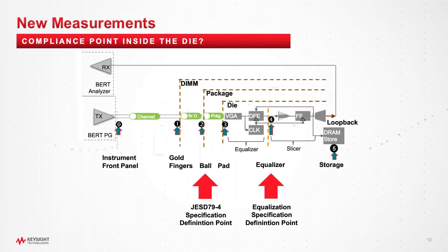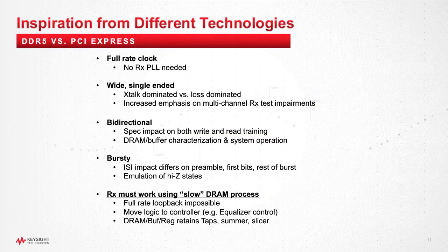And this is a couple of examples of the monkey wrenches, if you will, that are being thrown into the mix when we go past DDR4. There's really a whole set of things that are different between a memory interface and a traditional high-speed serial interface that need to be taken into account when figuring out just how you do a design that runs faster than 3.2, and how you specify a set of devices that can support that.